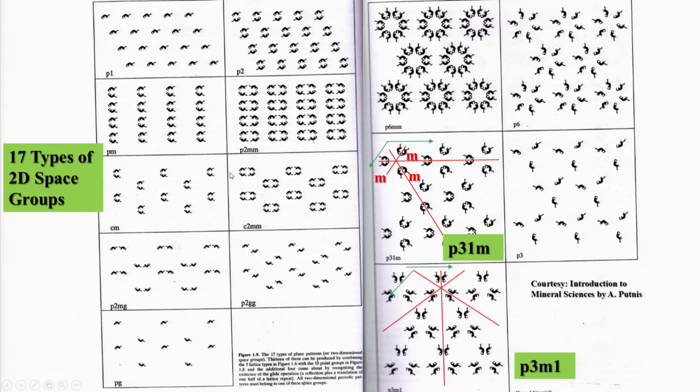Very simple. You have a mirror plane of this orientation, and you have also a mirror plane of this orientation. So, if you have a starting dinosaur motif here, after reflection it produces this, and with respect to this mirror plane, this reflection will produce this. Now, this pattern can be translated along this direction A, and it can also be translated along B. So, if this is the distance 2B and this is A by 2B, if it is cos phi, and that condition is maintained, you develop this centered rectangular lattice, where 2 mm is combined with that. So, we call it C 2 mm.